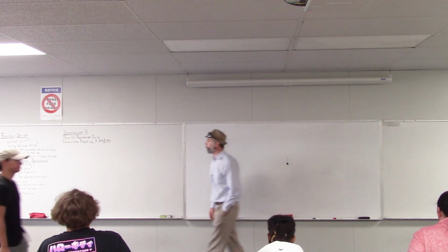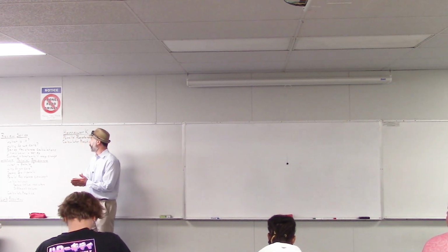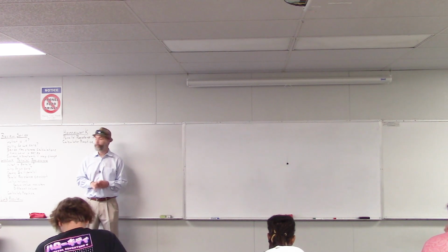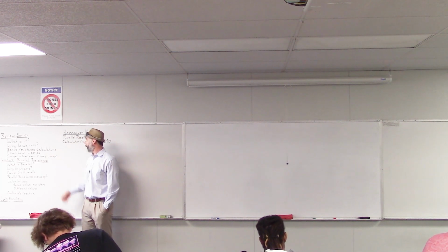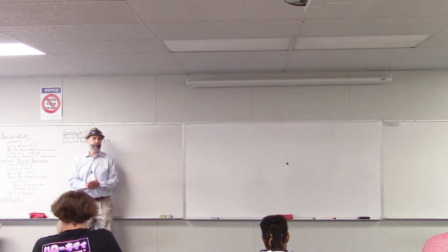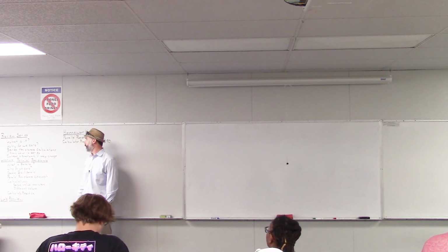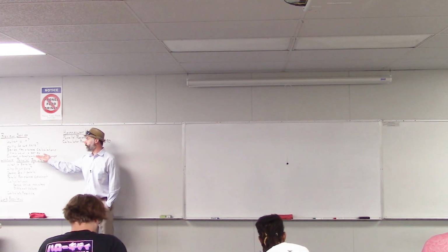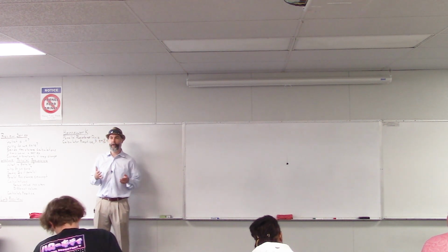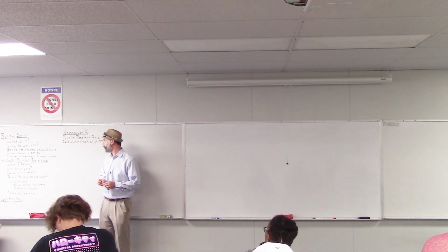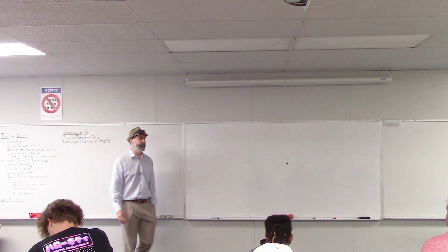Okay, so today we're going to start with a brief review of series. Last time we talked about series circuits, so we'll remember what series means, why we care about it, and then how we can calculate resistance in a series circuit, find an equivalent resistance. And then we'll remember a little bit about Ohm's law in series, and we'll recall that when you have a series circuit, the current will be constant for all of the components, but the voltage might change from one component to another. Then we'll go on and do our lecture for today, which is about parallel circuits and parallel resistance.